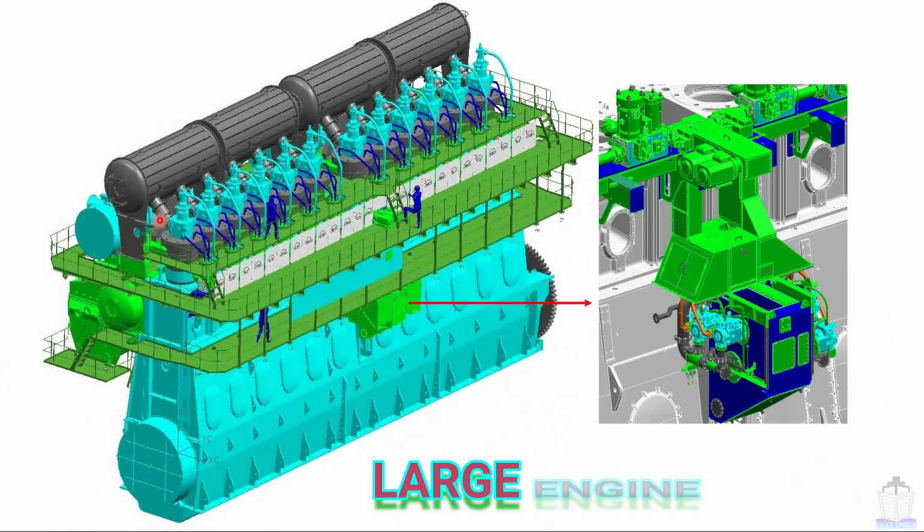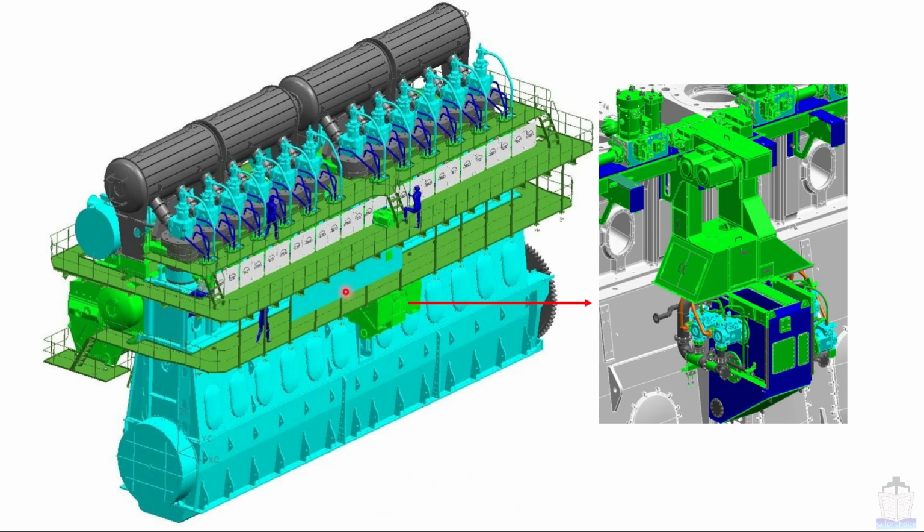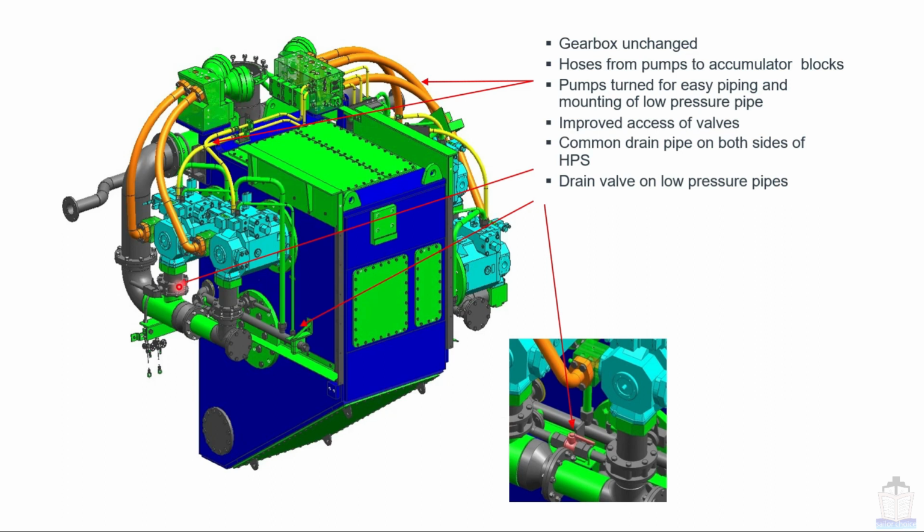Now if you talk about the larger engine, then obviously it will have more cylinders. In those types of engines, the hydraulic system pump assembly is situated in the middle of the engine, as you can see clearly in this picture. Here these two are starter pumps, and here all 3 or 5 HPS pumps are situated, right? Now moving next, you can see these two are electrically driven pumps, and here all 5 engine driven pumps are situated. Now going to see some more pictures related to the same construction. Here is the separate view of the engine driven HPS pump assembly.